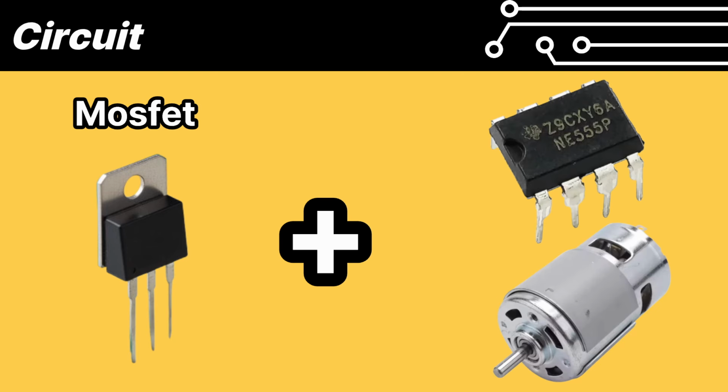MOSFETs are excellent for use in high-frequency applications or for controlling high-capacity DC power. They can be used in conjunction with timer ICs to control high frequencies or in building power supply units. They are also suitable for driving larger motors.